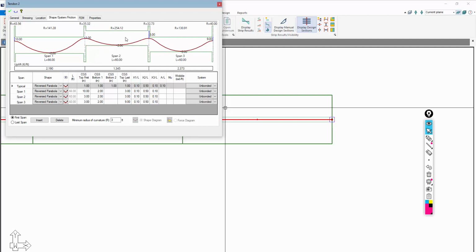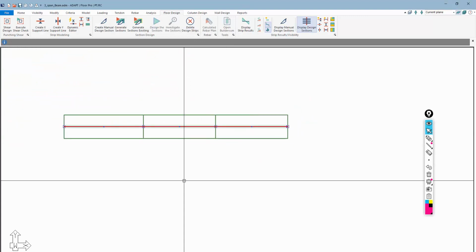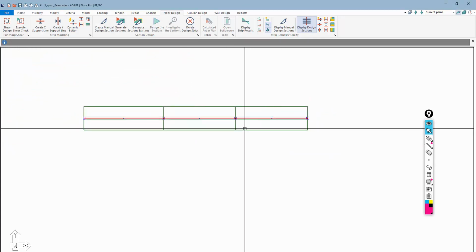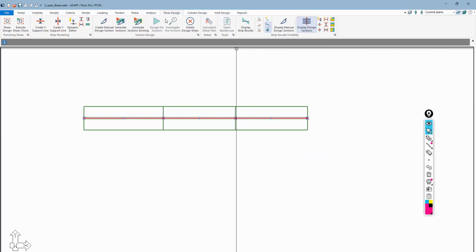Now here in this middle span, we don't really have a lot of drape because we're dictated by the tendon cutting through this edge here and this edge. So we might actually have to add additional tendons that are anchored up higher and drape down in order to control the stress in that span. I'll show you how to model that. We're not going to go through the entire design process of doing that, but we'll show you how you can model that also. So this is our starting point for the post-tensioning.